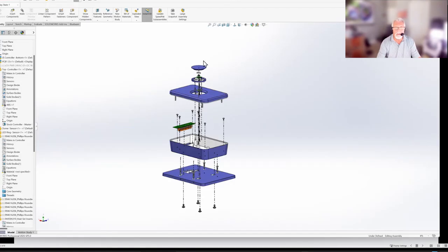Now, the other thing is if I select, it's called the breadcrumbs. And as you see here, when I select that part, you can see here it's given me all the assembly information constraints. I can go into the part actually and click the part. Now, if I come over here, click the part, and I hit the D key, the D key brings it right where your cursor is. SOLIDWORKS has done a great job of bringing those commands right to your cursor, so that you can come here and edit your constraints, but then also your part. You can edit your part right directly from here. So that's a nice feature there.